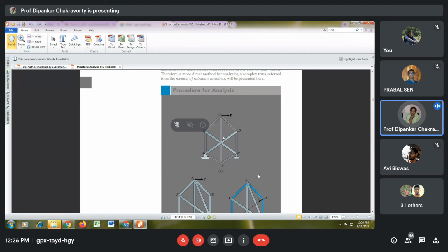So number of unknowns: number of members 9, number of reactions 3, so 12. How many joints? 6. This is not a joint. So how many equations? 12. So determinate. Okay. Yes, sir.